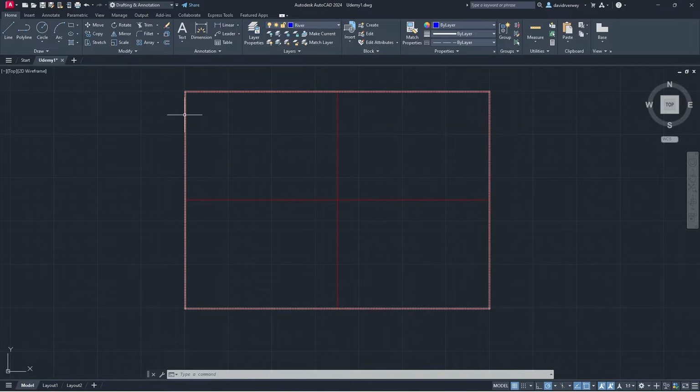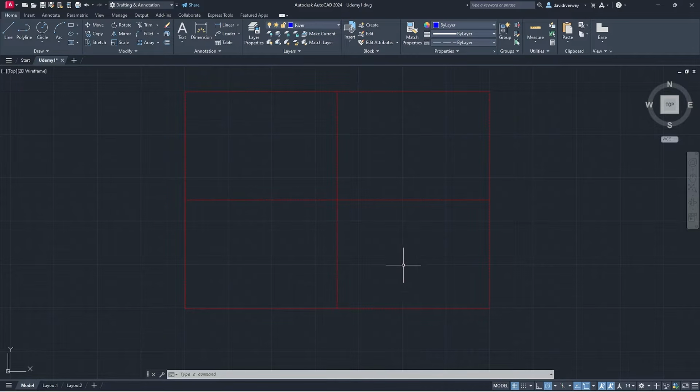And what we're going to do is we're going to draw a river. So, we're in the layers command. I didn't show you how to do splines yet, but this is a great way to teach you guys how to do splines. So come down to draw. Just click down, and you're going to see there is a command around here called spline. So there's spline fit, there's spline CV. We're just going to do spline fit. So if you click that, you're going to have the spline command.